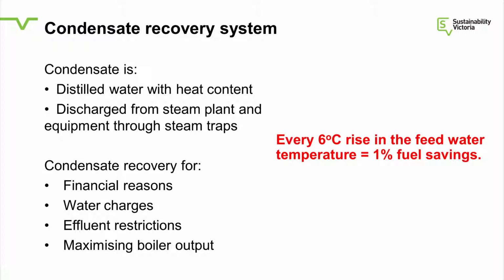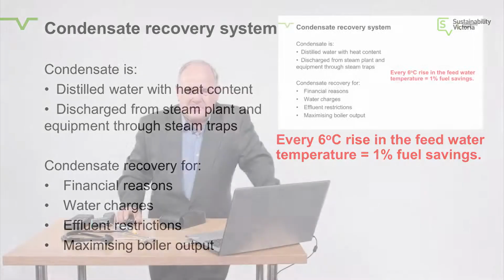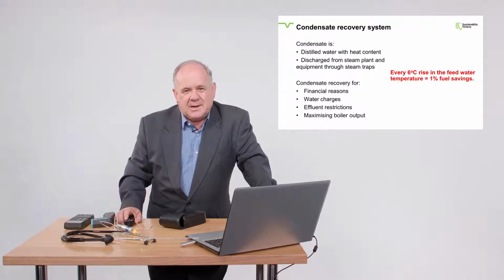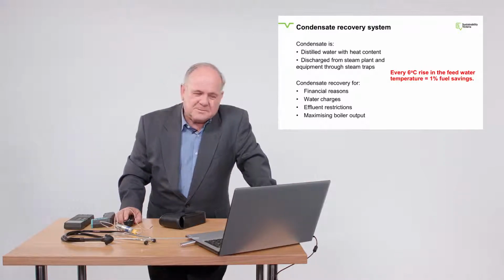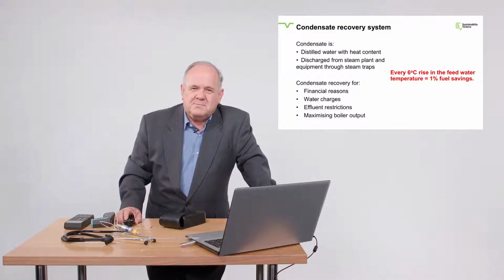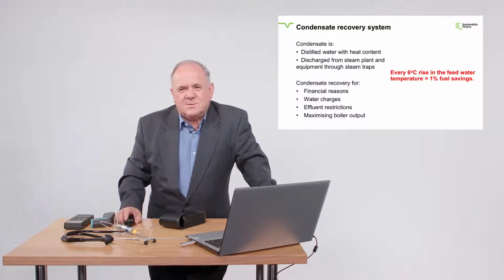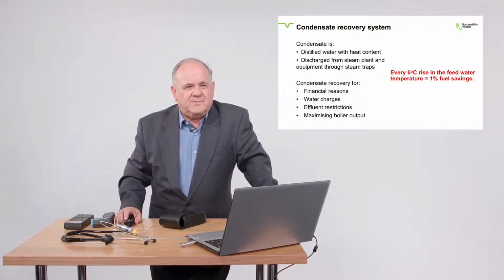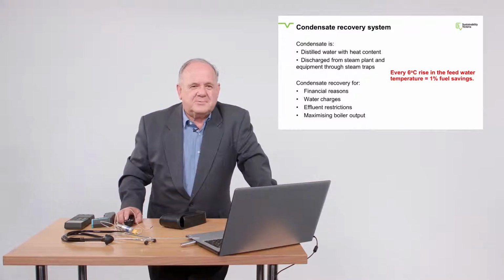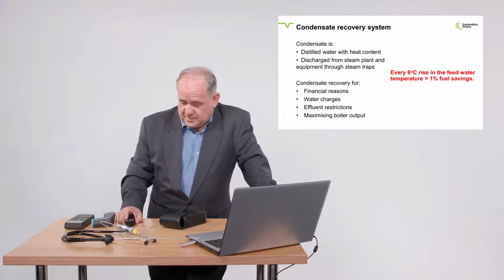6 degrees is worth 1%. It's a large number. If you've got a big gas bill and you're paying a hell of a lot of money, and then you're running the condensate, you're paying for hot water, chemicals and heat. Sometimes people don't return condensates because it's too far to run it back or whatever, but do your sums. The last time someone might have looked at it was 20 or 30 years ago when gas was $2.50. Now it's $12. So maybe it's worth reconsidering it, because the cost of actually returning it won't have gone up much in real terms.